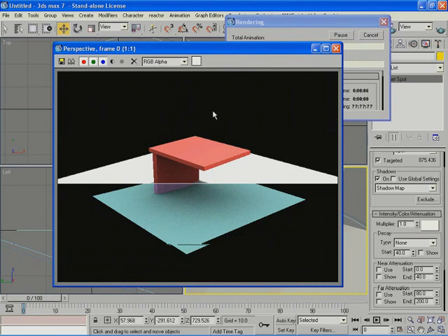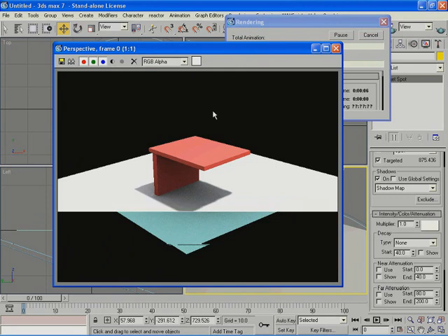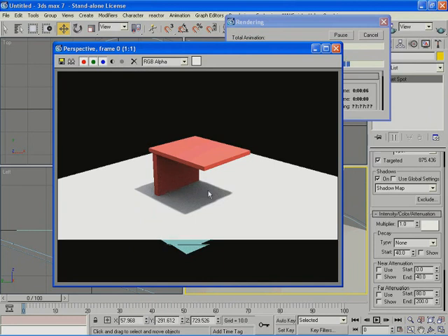And to get realism, I need ambient occlusion, which is provided by the shadows generated by the skylight. So this is the simplest way of creating a sunlight system. The only thing that I don't have, which should be required for a realistic daylight rendering, is the color bleed, which means that whenever I have a red material here, I should have a reddish tint here underneath it because of the light rays that would be bouncing. I do not get this using the default skylight system. So in case I required color bleeding, I have to use something else, which we'll see in the next example.